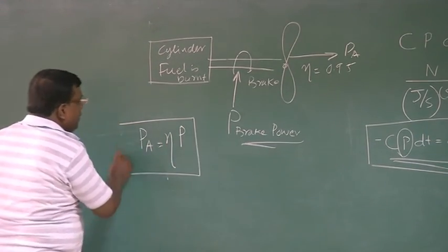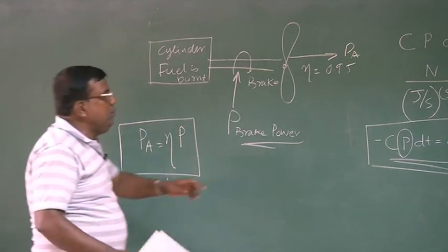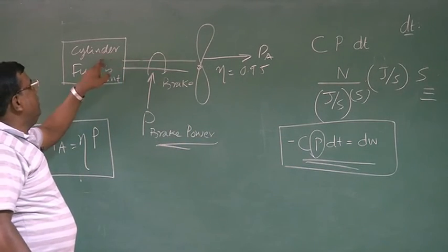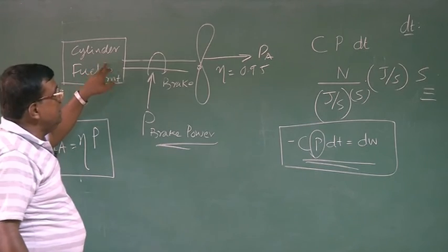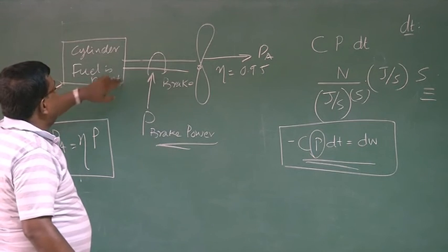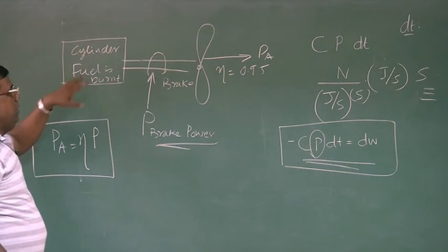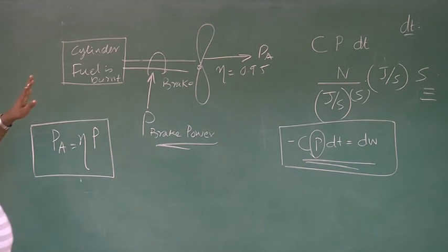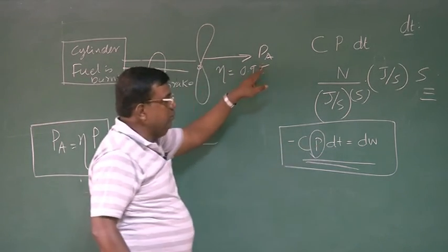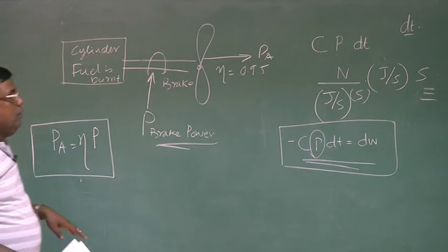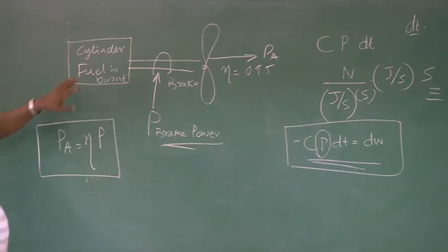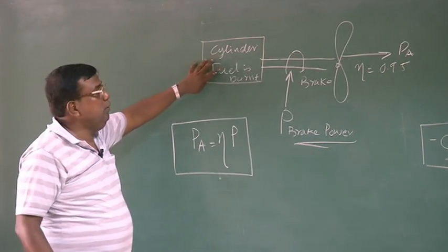This is extremely important. So when you are talking about dW, I am concentrating on the power here, so I am linking myself to this. That is why C, the specific fuel consumption, is a property of the engine, as well as having some relation with the environment. I am stressing that this power is not the power available. This power is the power at the brake. Why? Because we want to relate range or endurance via the fuel consumption. So we are concentrating here.